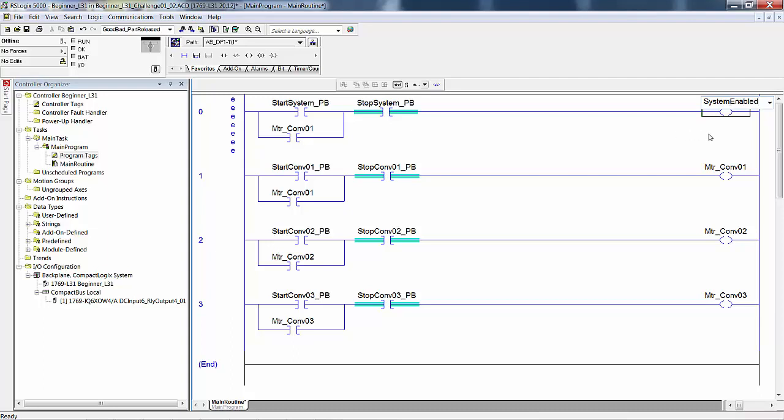And the rule of thumb that I use, if I can easily see the uppercase letter as a delimiter on those two words, then I leave it like that. In some cases, it doesn't show up real well, like if you have a lowercase l followed by an uppercase I, it looks like two lowercase l's or two i's. Then you want to use an underscore. In this case, this is good enough. This then gets dragged down to here, and there your rung is finished.